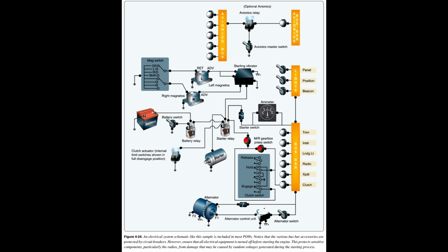The ammeter reflects current flowing to and from the battery. A charging ammeter indicates that the battery is being charged. This is normal after an engine start since the battery power used in starting is being replaced. After the battery is charged, the ammeter should stabilize near zero since the alternator or generator is supplying the electrical